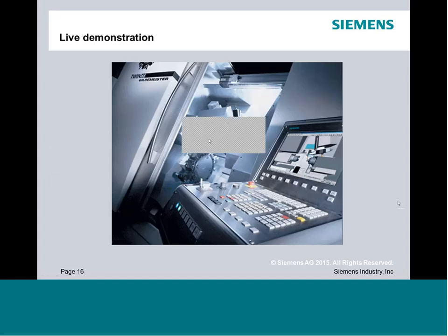So to just kind of demonstrate that a little bit, I do want to jump over to Sinutrain. Sinutrain is that machine emulator, the virtual emulator that's going to mimic the physical control or machine under control. And I'm going to delete a couple tools, and we'll build a couple tools from scratch here. I wanted to build certainly an OD tool, and we can go through and kind of feed the fields like we were just talking about, and maybe we'll build a neutral tool just to kind of go through it.